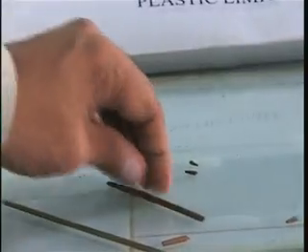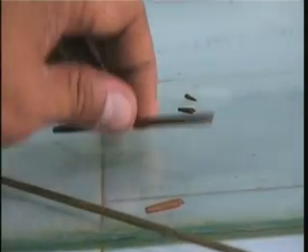Okay, so the moisture content of this specimen is barely allowing us to roll a thread of 3 millimeter diameter. As soon as we try to go finer, it is starting to crumble. So the moisture content of this piece of thread is going to be the plastic limit.